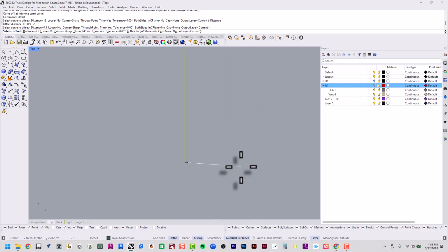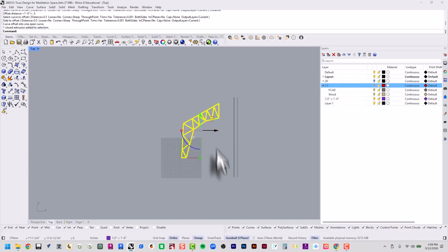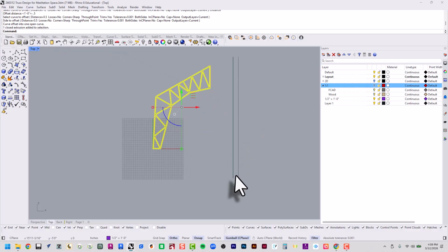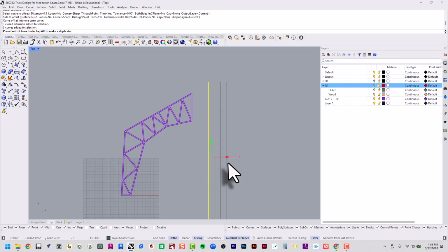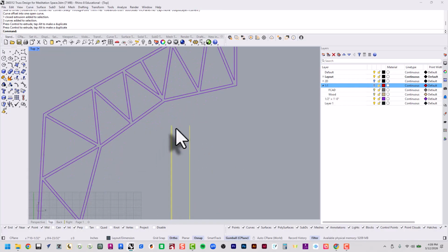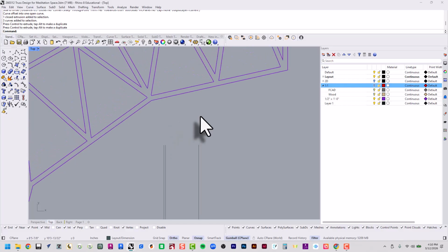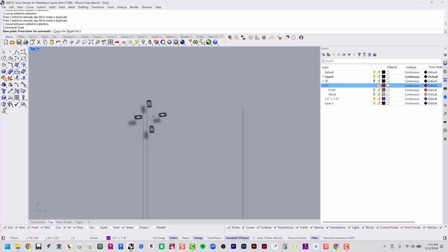And then I'm going to select my 3D object. I want to make sure it's a closed extrusion. It makes it better for 3D printing. And let's scooch this over just so we can visually see this a little bit better when I do my magic. So to scale this down to half inches equal to a foot, I'm going to select that truss, scale, enter. My base point is going to be the end point of the first line that I made.